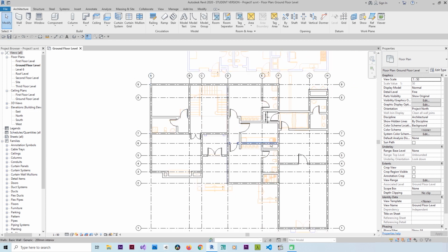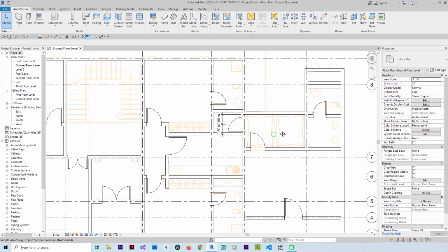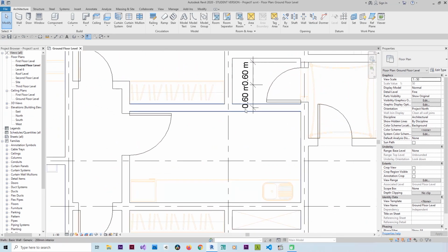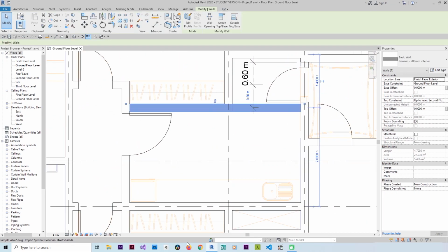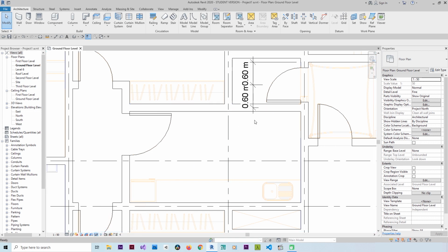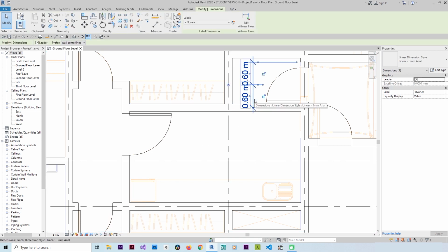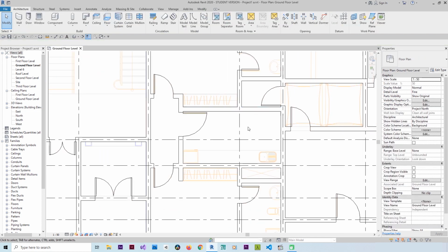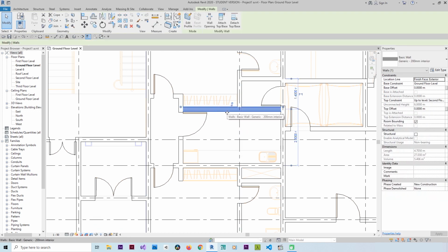Now I have some wall openings, like here. If I hide this element, I will find the wall opening here. I can reset it with Reset Temporary. With this tool, I can select the element and go to Isolate, temporary isolate.